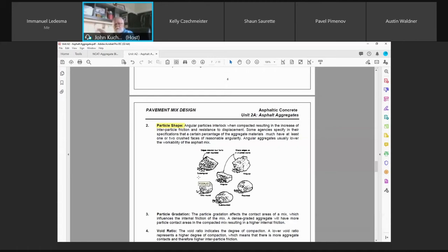The finer material is going to go through, and you might go through your cone crusher, impact crusher, and you're breaking it down. So those big cobbles and boulders are being crushed. You're going to get some crushed, but you're also going to get some of the smaller aggregates that are maybe subangular, formed by natural environmental factors.